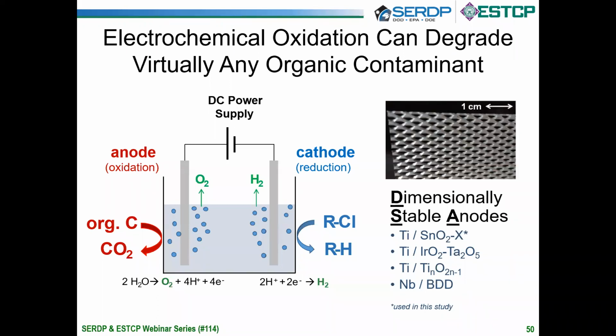But the thing is that we're doing this in water, of course, and water is a great redox buffer, and it can be oxidized and reduced itself. And so a lot of the electrons that we're providing, or really most of the electrons, go into the anodic oxidation of water to oxygen and into the cathodic reduction of protons to hydrogen. So in a way, it is a wasteful process if we're just doing this electrochemically, and thus arose the idea of using these gases to stimulate biodegradation processes.